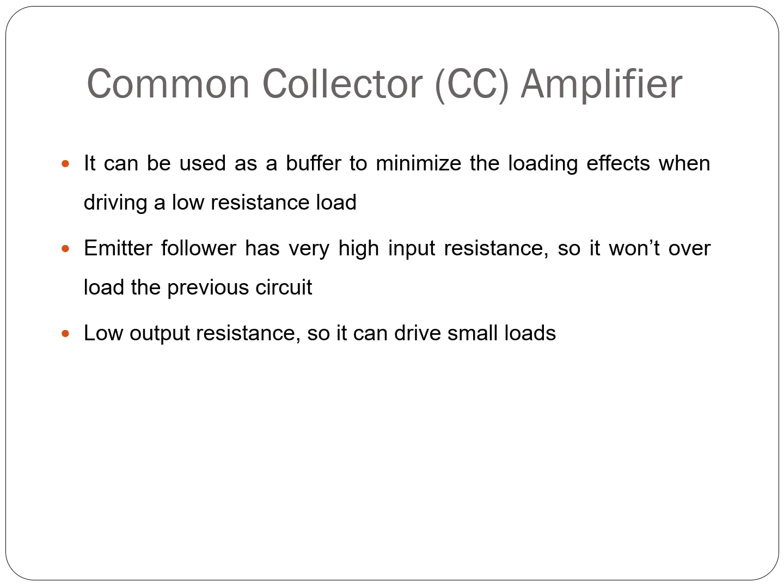The common collector as a buffer. Let's talk about one of the most valuable real world uses of the common collector amplifier, which is a buffer. And here's the problem that it solves. When a circuit with high output resistance tries to drive a low resistance load, the signal can drop or it can distort, and that's called the loading effect.